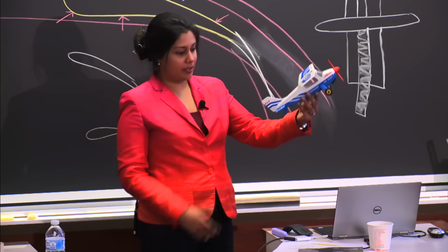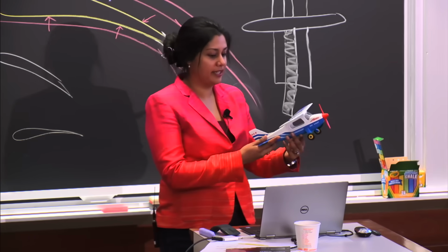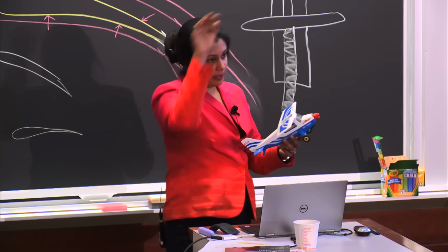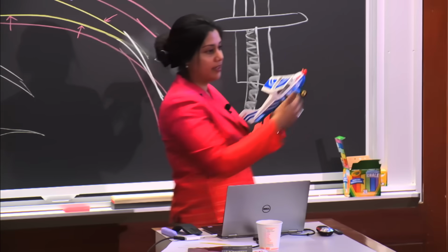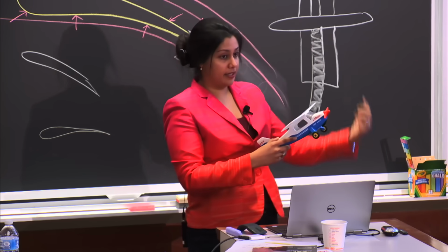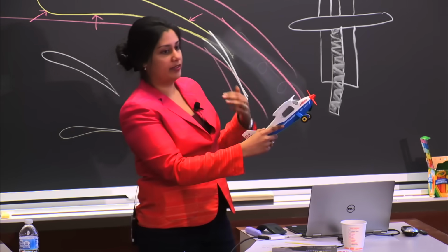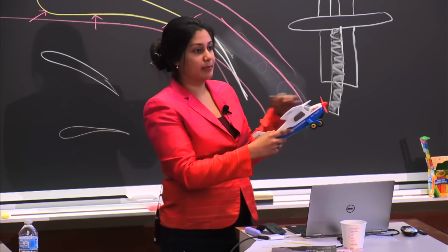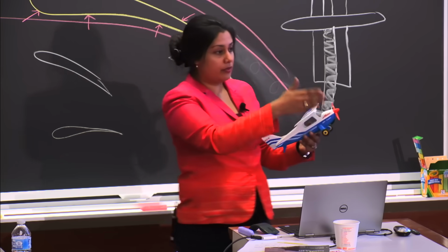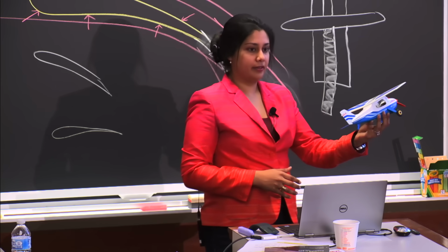If you're pitched up and you have a high angle of attack and you're either climbing or in slow flight, you have this tendency where because you're angled to the wind, the right propeller blade, which is descending, is cutting into the air that's coming in. So it's actually generating more thrust. Whereas the ascending left propeller blade, the one going up on the left side, is coming away from the wind that's coming at it, and so it's not generating as much thrust as the right propeller blade. That causes the center of thrust to move towards the right, and that creates a little bit of a yaw tendency of the airplane.